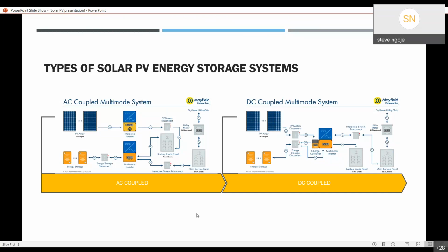I know of good brands, and most of them can only do around 250 volts at maximum for their largest charge controller. If you compare that to PV inverters, that can go up to about 1500 volts, they can take in a lot of panels. So for industrial scale, where you may need energy storage systems, AC coupling will be a benefit.